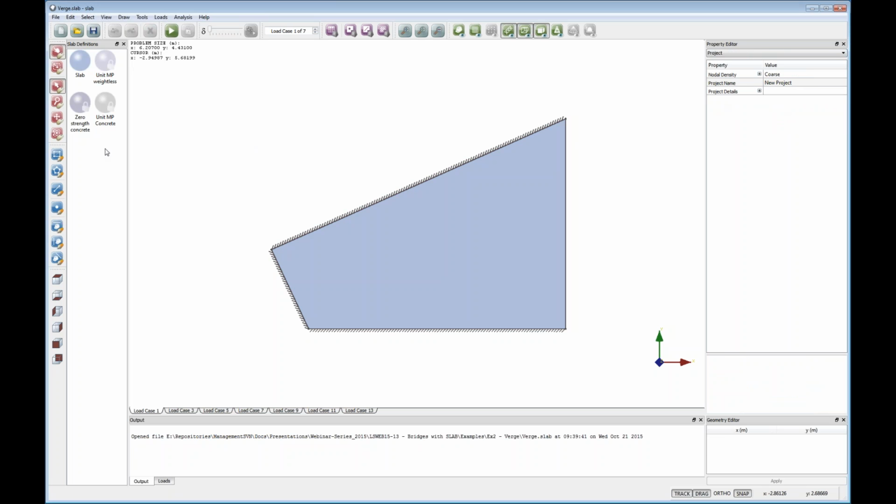And then we need to generate some slab mechanical properties, and if we click on there, you can see we've already predefined one called slab, where the first direction has a positive MP value of 90, and also in the second direction as well. The thickness is 0.31 meters, and again the unit weight 24. And then all we do to put the material onto the slab is to drag and drop it. In this case, it's going to say it's already present in this solid because I opened the file, but it's as simple as that.